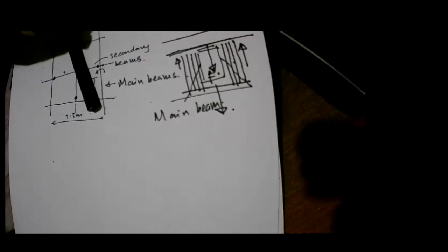Basically you will hang the links from the top bars, so that the concrete will not crack and fall. So when you have secondary beams, you have to be a little careful, and provide some extra reinforcement in the main beam in the form of links to ensure that the secondary beam is firmly kept in position. So that's one of the requirements.